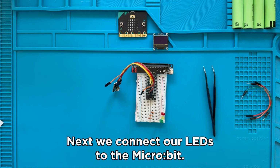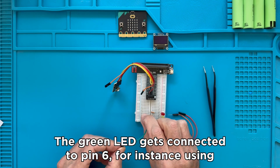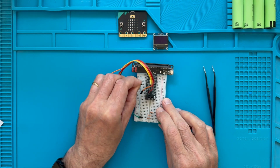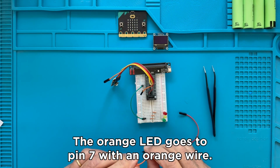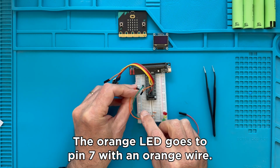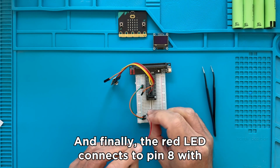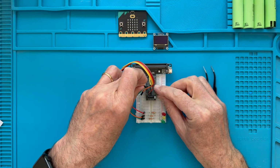Next, we connect our LEDs to the microbit. The green LED gets connected to pin 6, for instance, using a green wire. The orange LED goes to pin 7 with an orange wire. And finally, the red LED connects to pin 8 with a red wire.